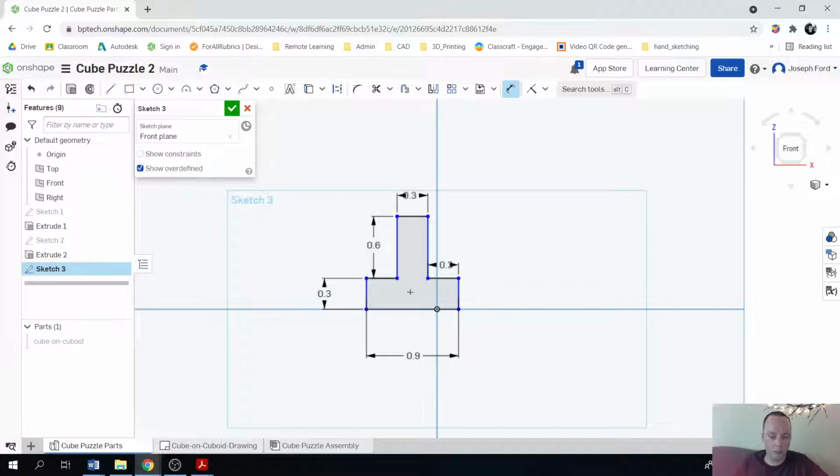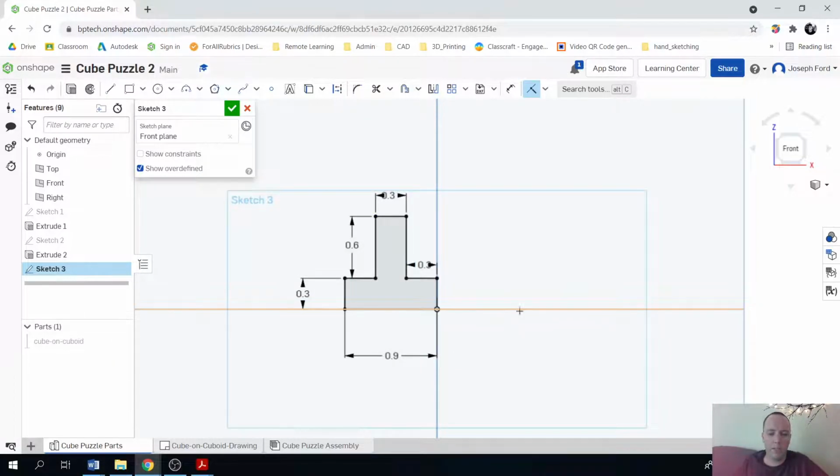And then, what do I have here? I need to identify something else. And I don't think I do. Okay, I think what's happening is the origin isn't at play anymore. So I'm going to click on coincide, which is up here, or I key is the hotkey for that. Click on this corner, click on the origin, and then it moves over your whole drawing.